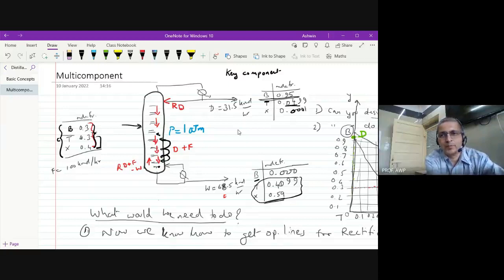In fact, what I would suggest you do is switch from the rectification line to the stripping line when you are closer to toluene composition, and see how the tray by tray composition looks. Or you switch over when the benzene composition is near the feed section, to whatever the tray composition is there, and then you see how it affects. So you do and see for yourself where we should switch. Choice is yours. All right.